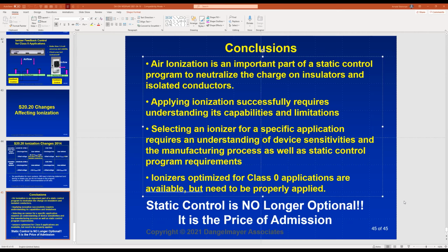Now the charge plate monitor, the voltage it's generating, can it damage highly sensitive components at all? The charge plate monitor, certainly you've got a charger for the charge plate monitor that will charge that plate to 1,000 volts. And you could take that charger and destroy everything in your work area, probably. Okay. So basically, in general, when we're doing ionizer measurements, we make sure that there's no product on the work surface at that particular time. But as long as you're careful and don't touch the product, you're not going to damage it with the ionizer measurement.